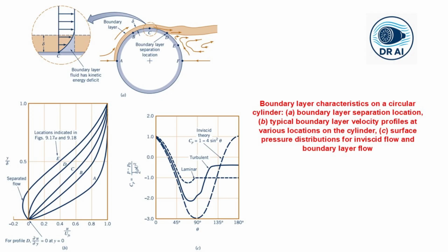So, this is the boundary layer separation. Beyond this point, we get a reverse flow near the wall. The boundary layer lifts off, creating a wake of recirculating fluid. So the separated region has much lower pressure than the front, creating the pressure drag, even though the viscous shear stress itself might be small. So this explains D'Alembert's paradox.